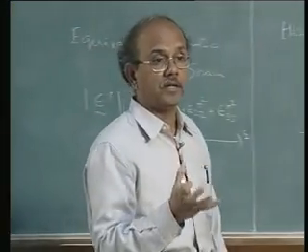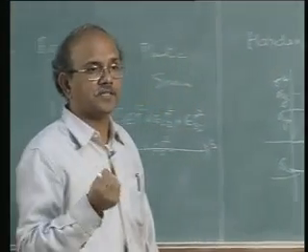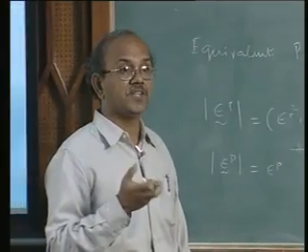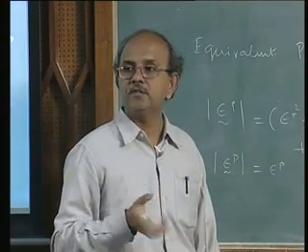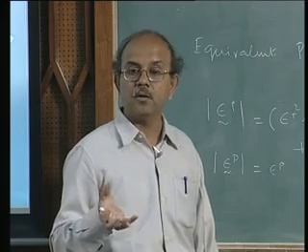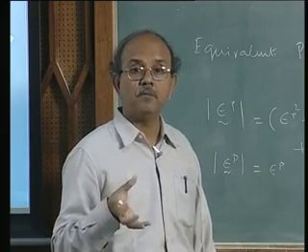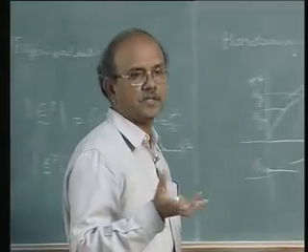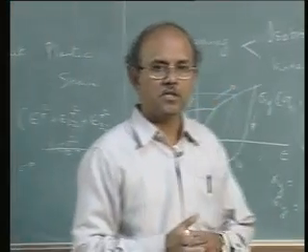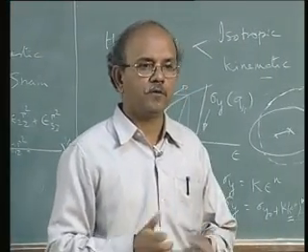Poisson's ratio effect will be there, exactly. So, I should have a Poisson's ratio effect, but what would be the Poisson's ratio in a plastic regime for plastic strain? 0.5. Yeah. Why is it 0.5? Incompressibility condition, yes. The incompressibility condition has to be satisfied in the plastic strains. So, the Poisson's ratio will be 0.5.